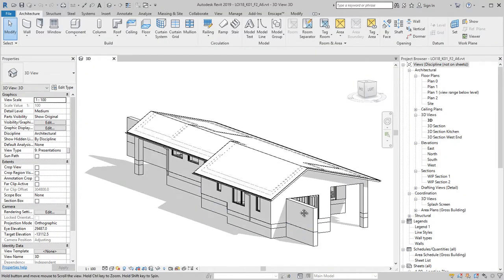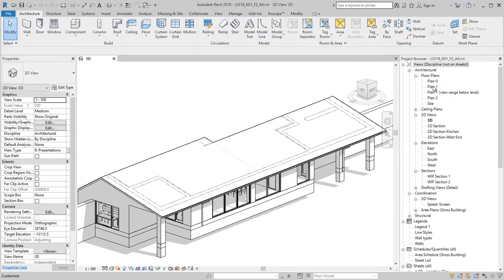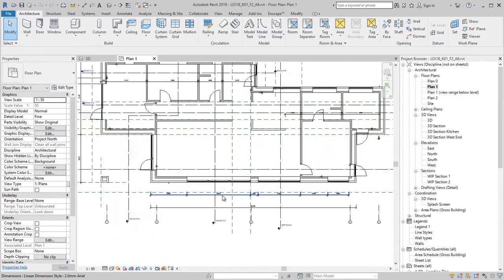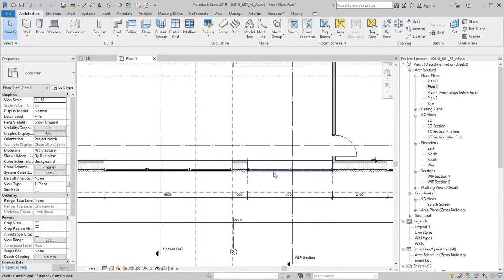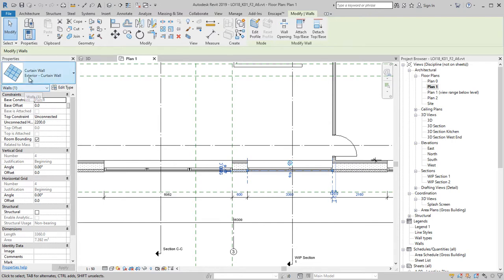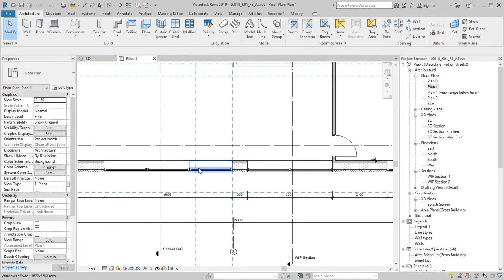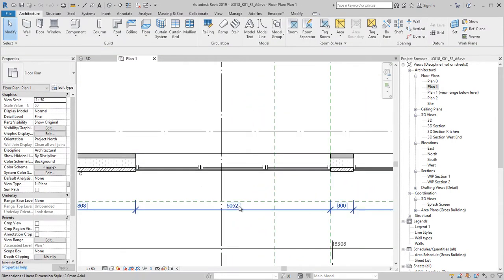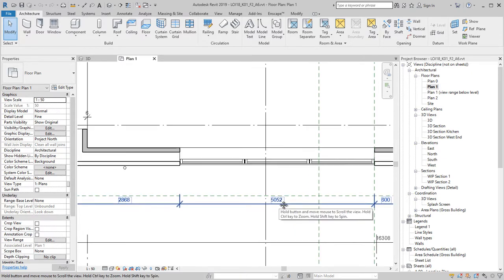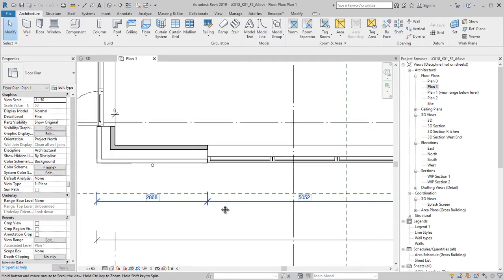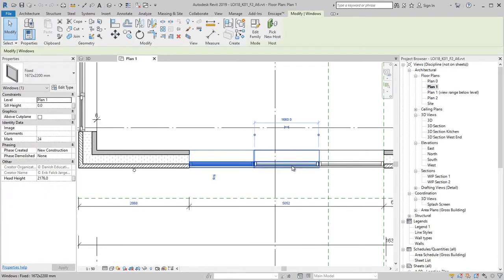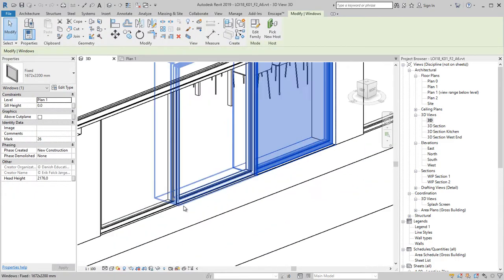In the early design phases, the use of curtain wall is very intuitive, but if it's a window or door delivered by a window manufacturer, then it's a window and not a curtain wall. Instead of having a curtain wall like this, I have created 3 equal size windows, and that will make the ordering of these windows very easy just by taking out the schedule of all window sizes. And as you can see, it fits into the brick measurements, of course.